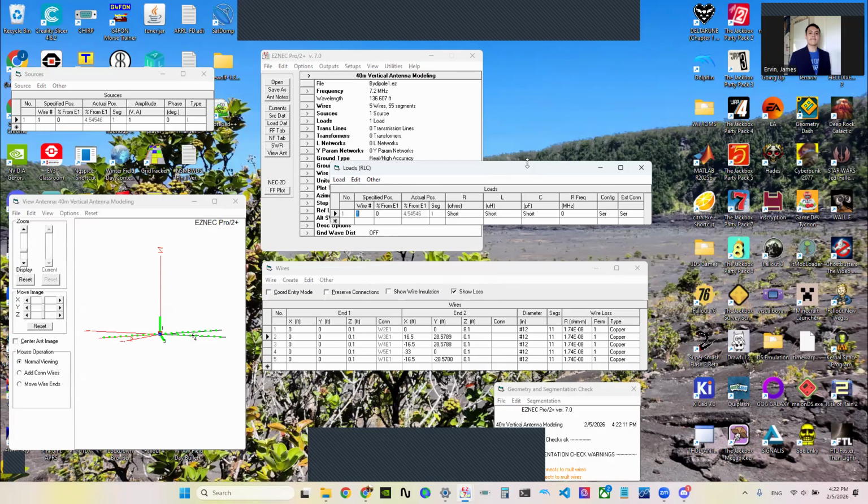So what you're going to do is press wire segment number one. Just type in wire segment number one, and apply the load 0% from the end. So basically, what this looks like construction-wise is you take the center pin of the coax, or right from your transmission line, and stick an inductor right on it. Then we're just going to put in 23 microhenries. Let me know when everyone has that. You're going to want to type here in your L tab 23 microhenries.